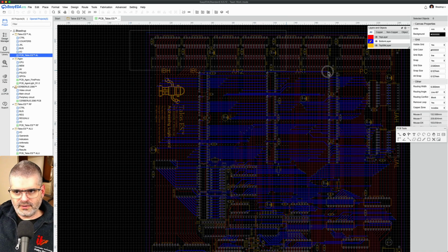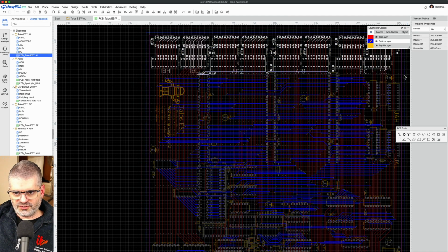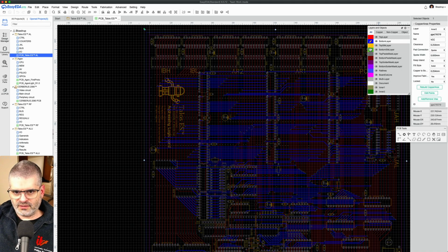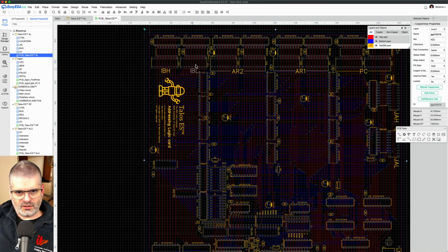Here on top are the circuits to visualize the contents of the internal bus. So the internal bus high and low, you visualize in these two LED bars, and then you visualize AR2 here, AR1 here, PC there, and the jump address high and the jump address low you visualize here. And then these 4 chips here, plus these 4 chips there, and these 4 chips here. These are the 3 counters, AR1, AR2, and the program counter. They are all in these chips.